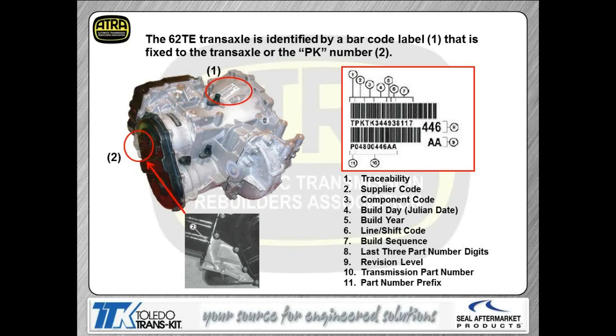One of the important things is this ID tag that you see here. If you're ordering parts for this transmission, you want to make sure you're getting the right stuff for the model that you're working on. So this matrix tag is on top of the bell housing. If it becomes damaged or missing, especially after it's gone through the parts washer, you can see that this PK number listed right here is also stamped in the back of the case right here in this corner. So if we lose the tag, we still have the PK number, and you should still be able to order anything you need or identify the transmission you're working on.